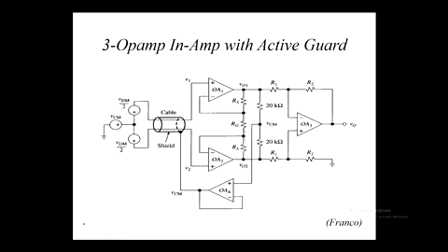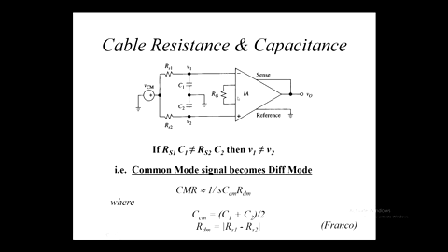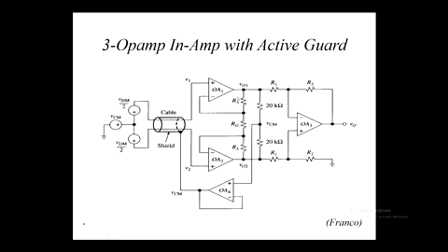So from a common mode point of view, there's no current flowing through RG. Good, okay. So that means that this is VC, and this point is VC also, and so is that one. So we've got a gain of 1 for common mode signals, remember? How did we analyse for diff mode?